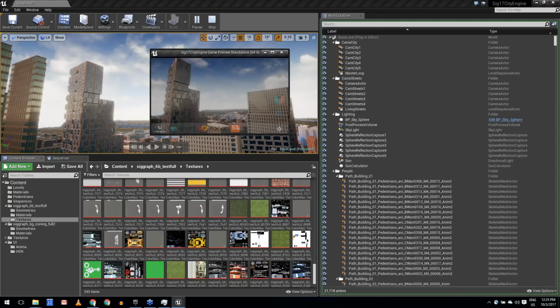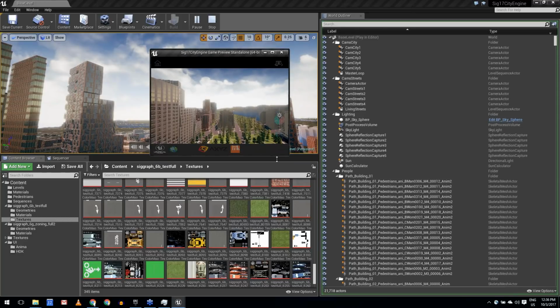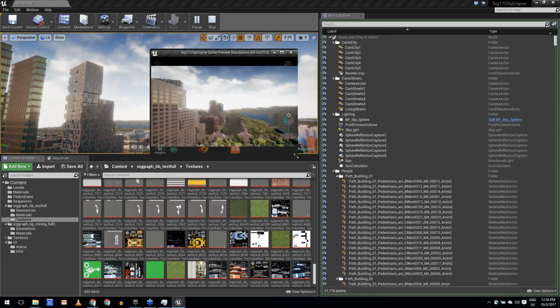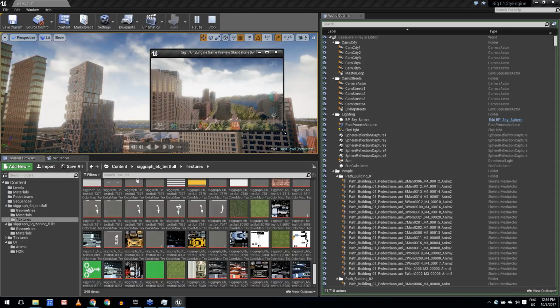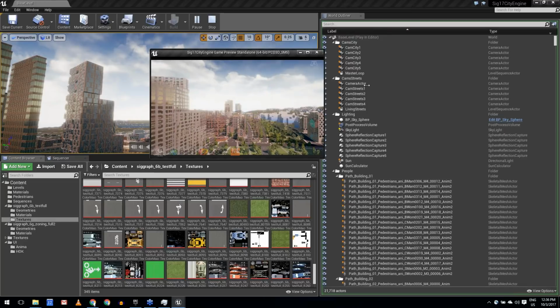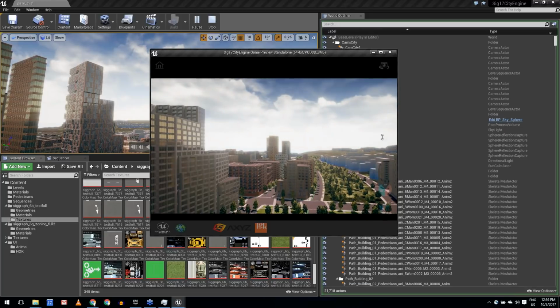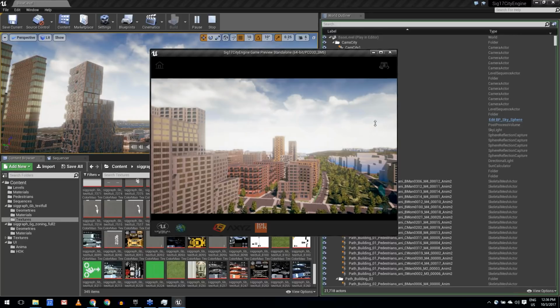Okay, to answer for the CityEngine regarding streaming of big data. CityEngine itself is actually more like an authoring tool, so we never aspire to do a whole metropolitan area. What we actually focus on is authoring the procedural rules. So we usually work on a small subset of the scene, and then when you're ready to export and go into your next tool in your workflow, you can select all and do a batch export. So you don't have to generate the whole scene in terms of CityEngine models inside CityEngine. You can let the export do that building by building, and so your machine will not die at this point.